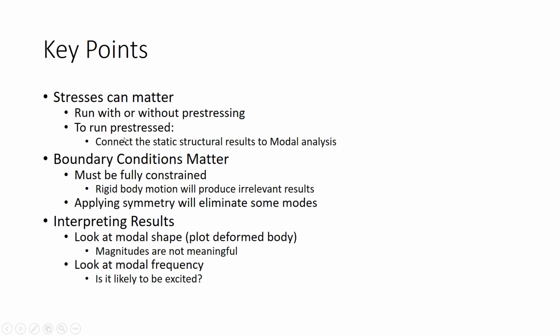If you want to run pre-stress, first you need to run a static solution and connect the static structural results to the modal analysis. The videos will show you how to do that, as well as the screen capture here in a minute. The other thing to understand is that sometimes you need to have nonlinear deflections on there to make sure that is handled adequately. As you'll see in the videos, that wasn't necessary in the examples that I ran, but it might be for your homework.